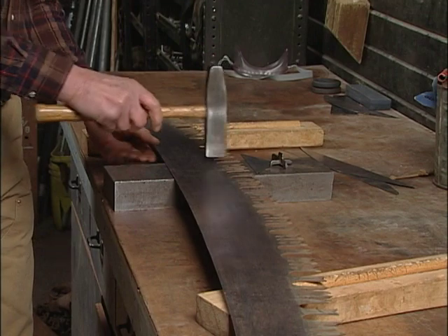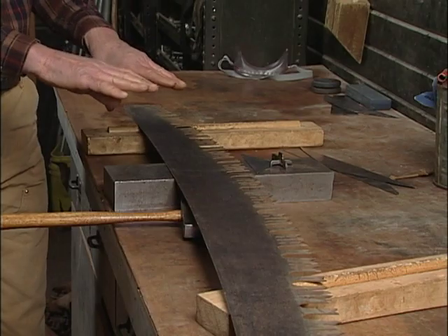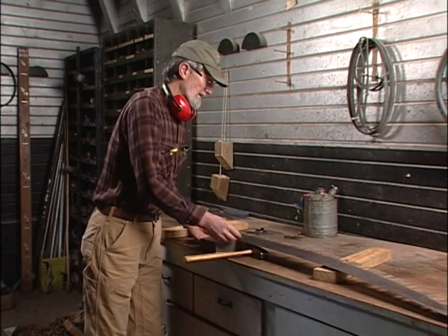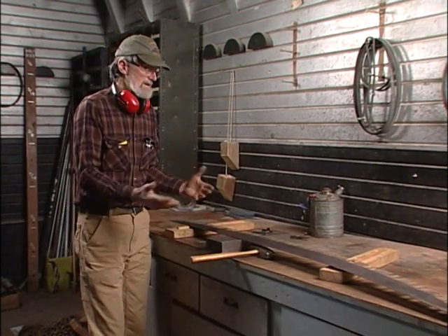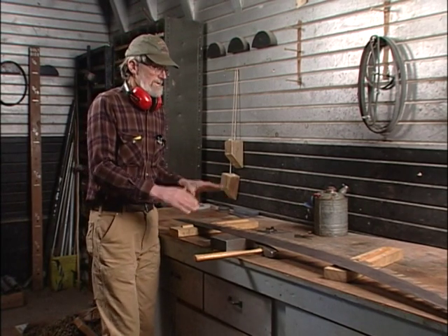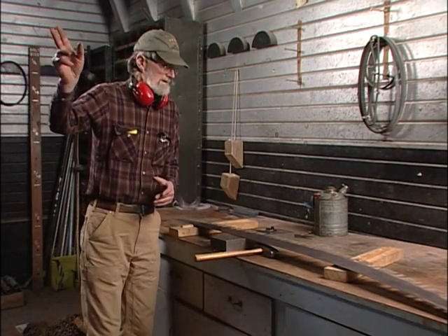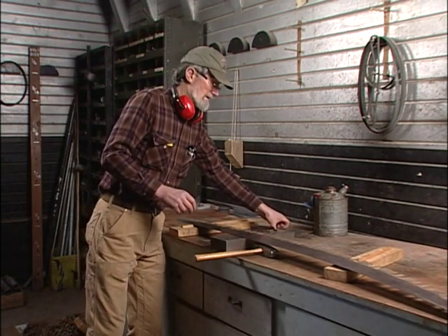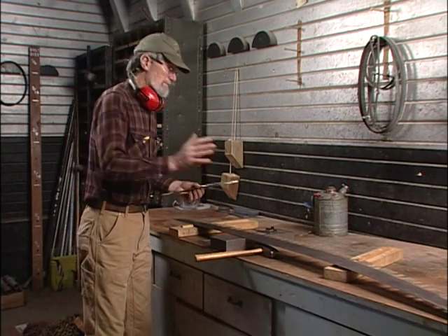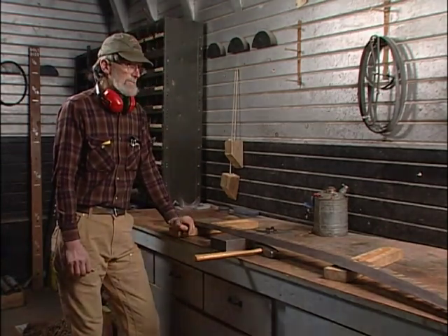Once I have done my initial hammering, there's a good chance that I haven't taken all of that kink out of there. Well, I'll have to hang it back up again and test it again with the straight edges. And it's a process that may take 3, 4, 5, 6 times to get that saw straightened out. So I'll hammer on it a little bit and put it up on the hanger, test it with the straight edges, and then find out how things are, and then I'll bring it back, lay it back on the anvil, and hammer it some more.